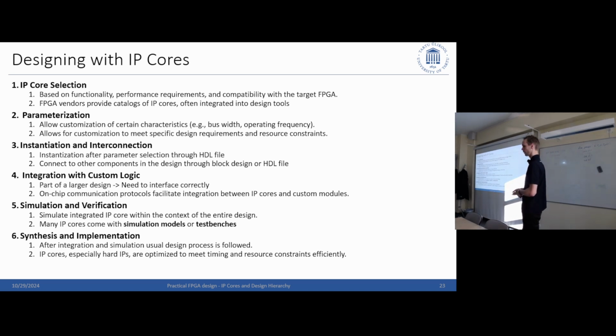Also, sometimes with IP cores, like the Vitis AI IP, the deep learning processing unit, for example, you can instantiate multiple of those. So if you select 3, then you have 3 times as many resources. But again, if you do not have the bus interface or the data bandwidth in other places, this is not going to be useful.